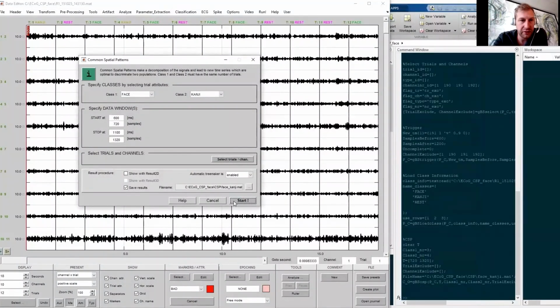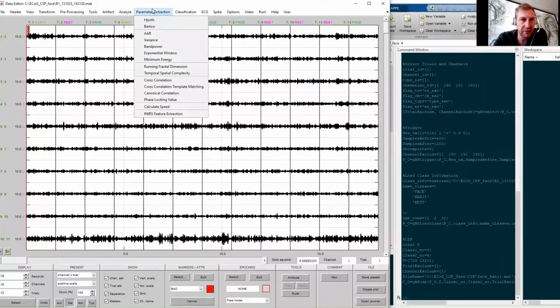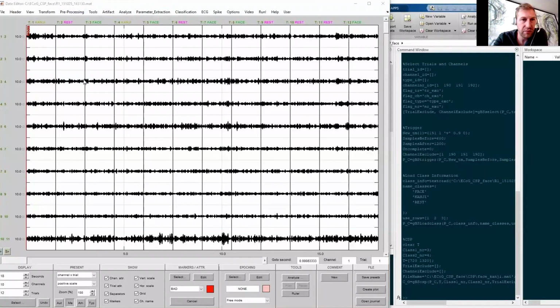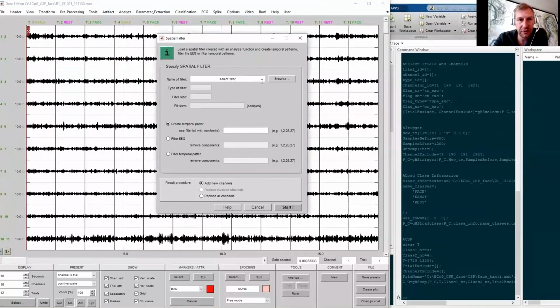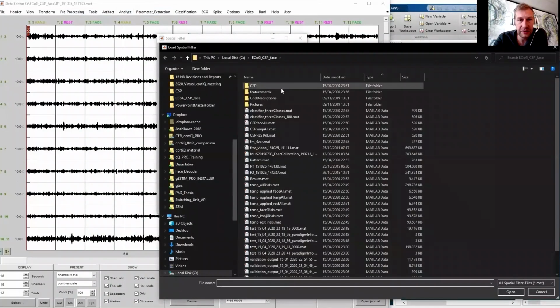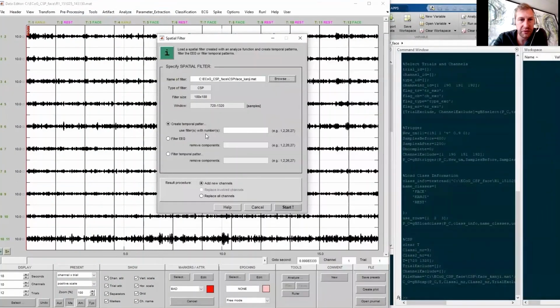This is a sort of principal component analysis where the signals of 2 classes are basically spatially filtered to maximize the variance for one class and minimize for the other. And this is then solved with an eigenvalue problem where we get, for the amount of channels, eigenvalues, and for each eigenvalue we get an eigenvector, which is a linear combination or spatial filter.